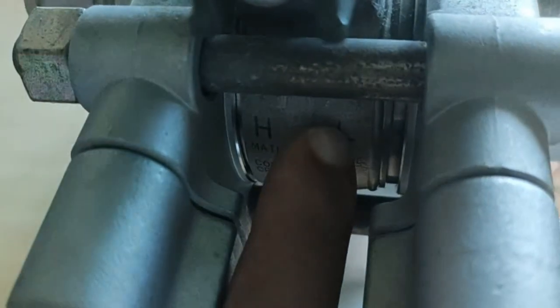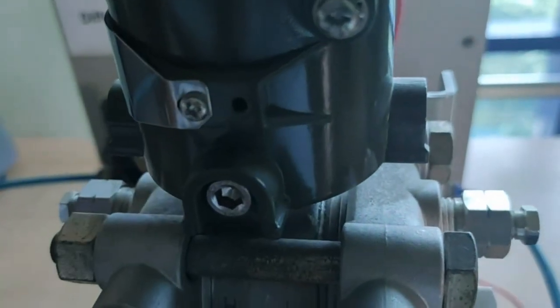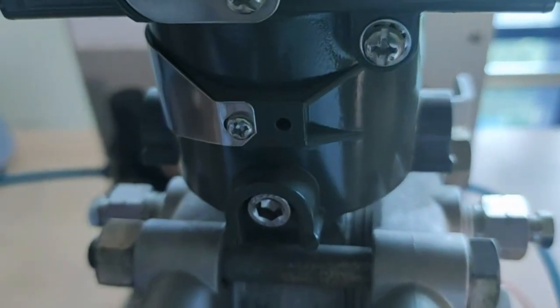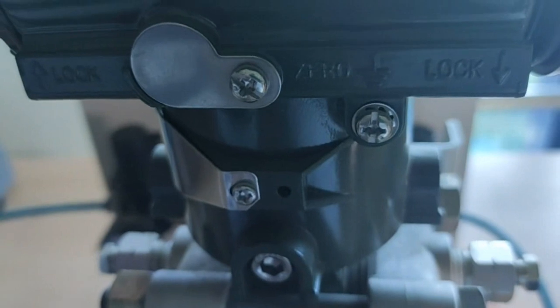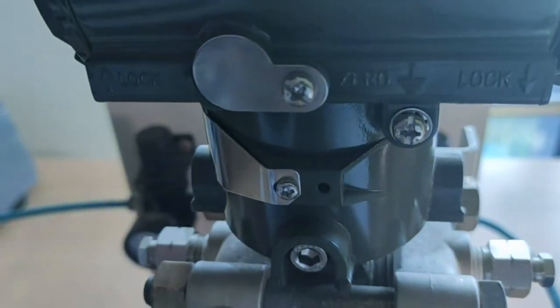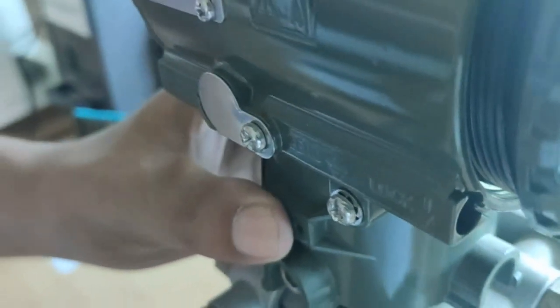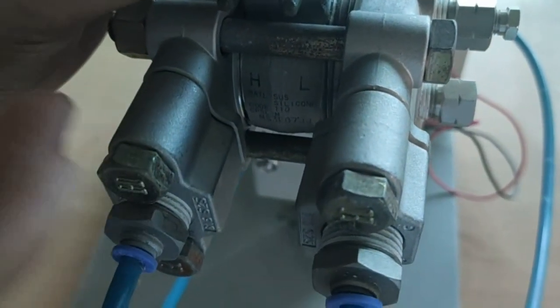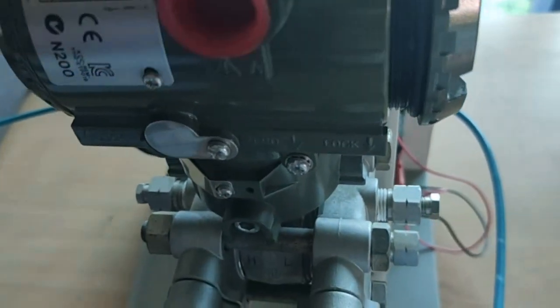After that this pressure drop will be sensed by a diaphragm element which is situated in this pressure transmitter. This diaphragm will deviate slightly according to the pressure drop, and this will be further processed into an electrical signal. We will get the output here. Various components are used for conditioning or amplification of this psi or bar or whatever pressure. In terms of pressure unit you get the physical quantity as pressure, and the electrical signal will come out here.